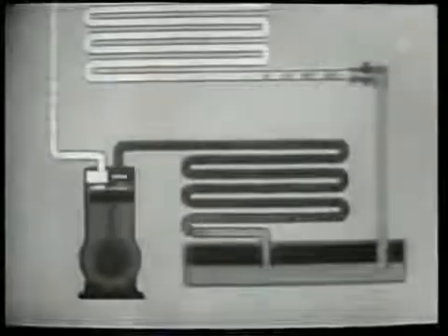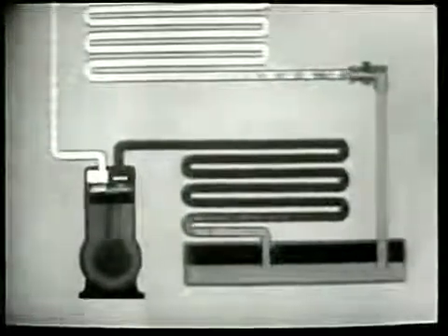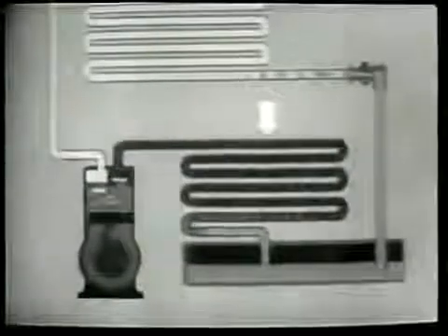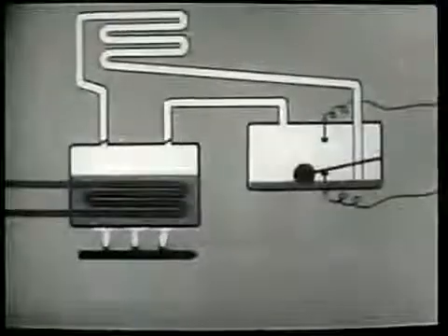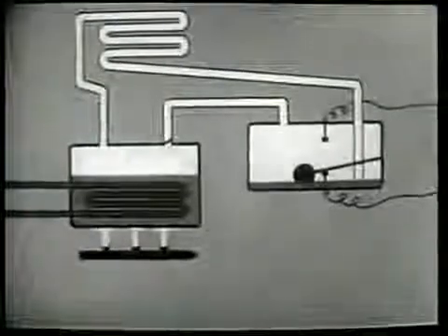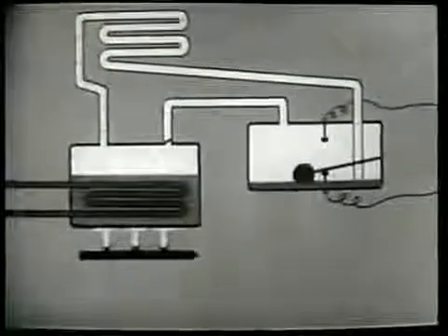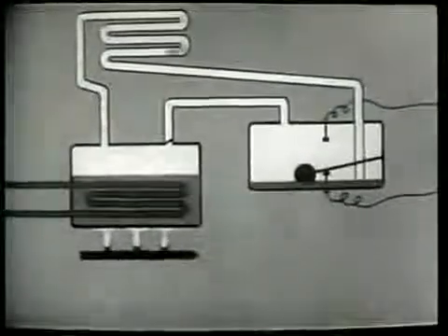In the compression cycle, the compressor forces the refrigerant through the system. The liquid refrigerant in the cooling unit absorbs heat, thereby cooling its surroundings, and changes to a gas. The gaseous refrigerant loses this heat in the condenser and changes back to a liquid. In the absorption system, heat energy provides the initial movement when the refrigerant is released as a gas from the absorbent. After losing its heat and liquefying in the condenser, it moves by gravity flow and collects in the cooling unit.